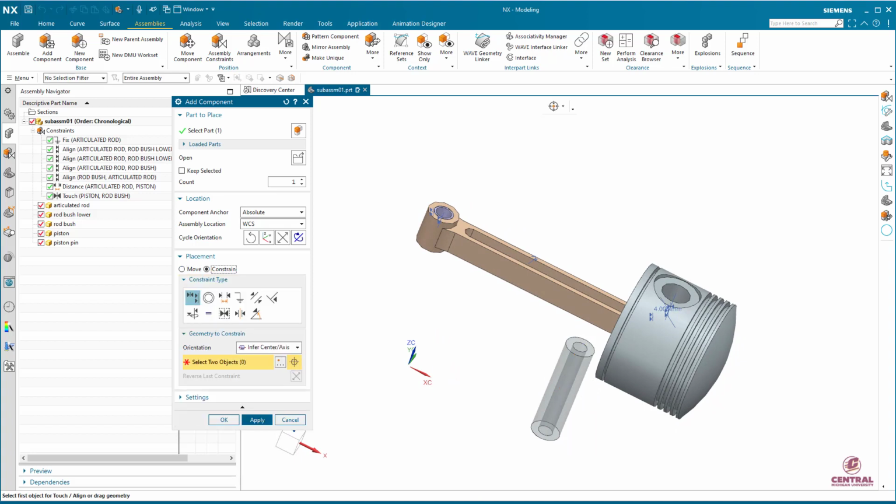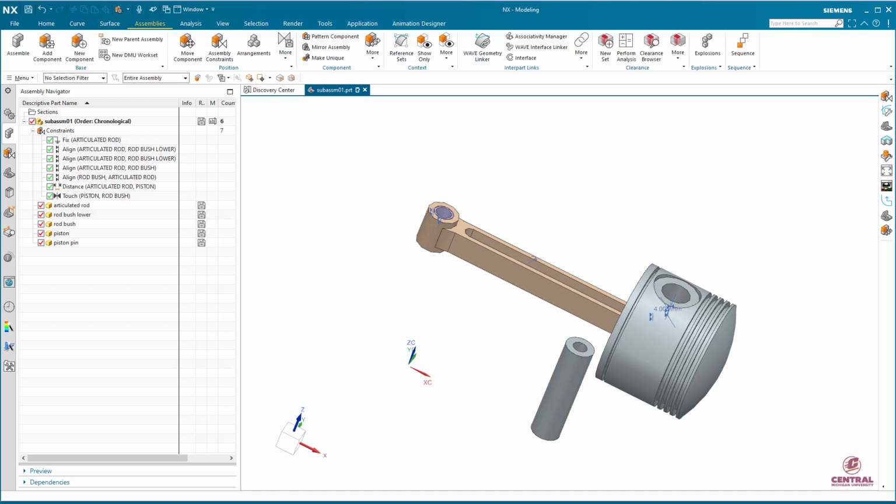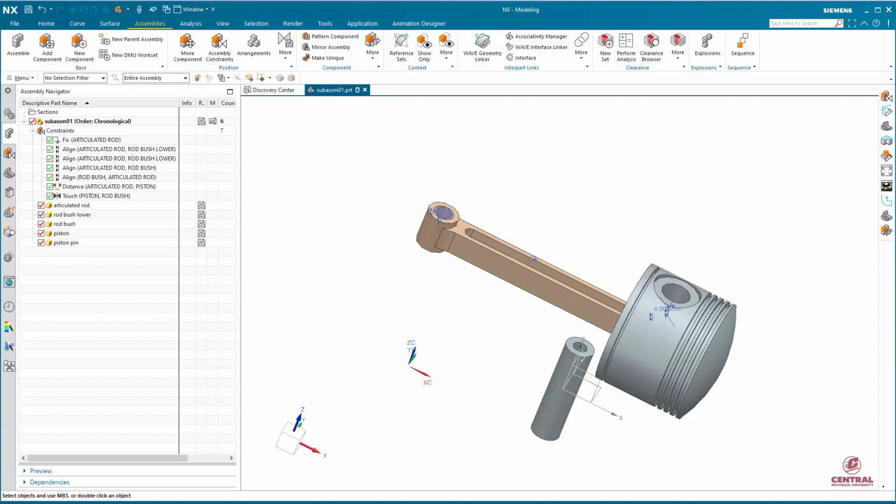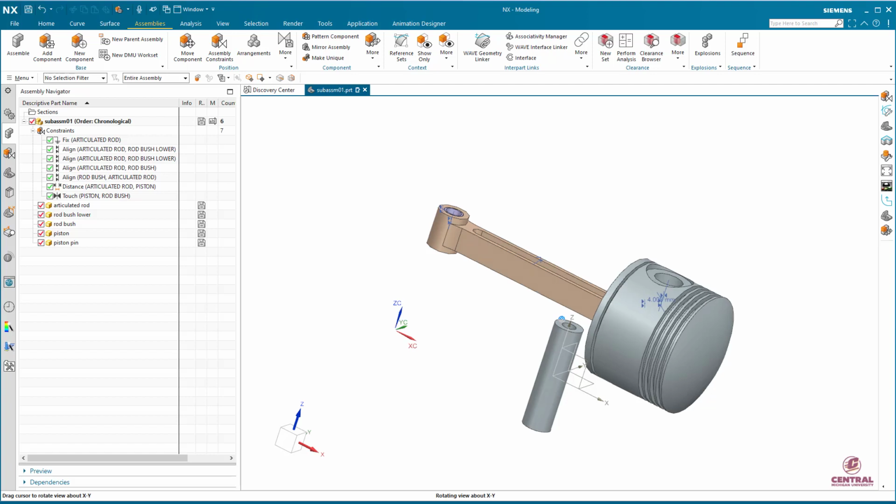So in this time when I do that, I want to make sure center of this is perfectly center of everything. Okay. So we already learned how to do it, which is utilizing the datum belong to the part. To do so, I need to activate those datum belong to the part. So it is forcing me again, get away. So I'm gonna just say okay, locate it, and right click over the part, replace reference set into entire part. By doing so, just like that, you are going to be able to see the datum belong to.